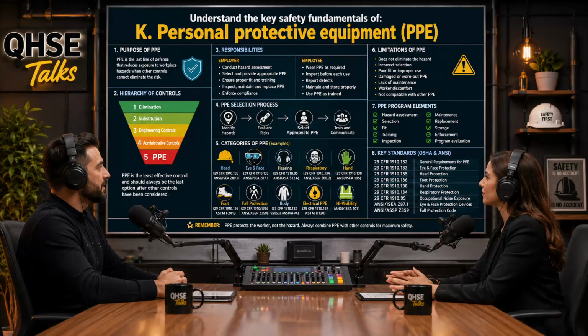It is a fully encapsulating vapor protective envelope. It has to endure brutal testing under standards like NFPA 1991, which ensures the material can withstand a battery of highly corrosive chemicals for hours without permeation. But let's look at the respiratory mechanics, because that's where it gets interesting. For breathing, the worker must use a pressure demand full-face SCBA. Yes. But the crucial detail is where the SCBA is located. It is worn entirely inside the encapsulating suit.